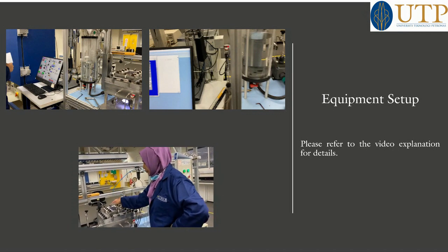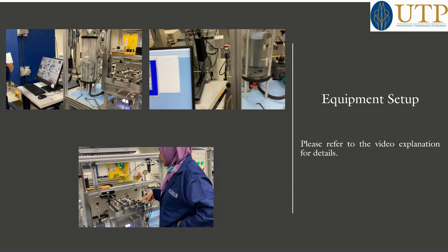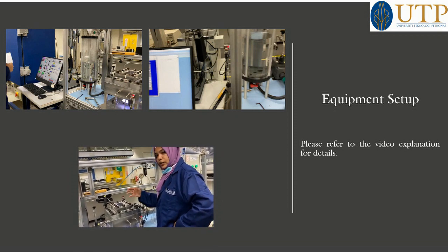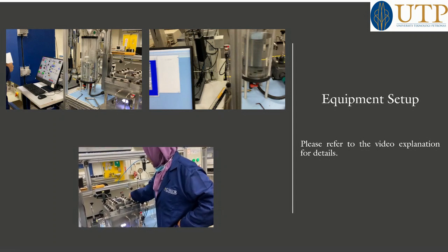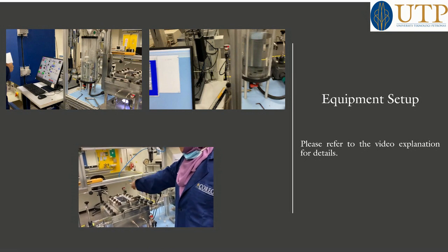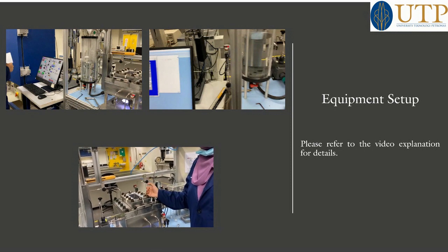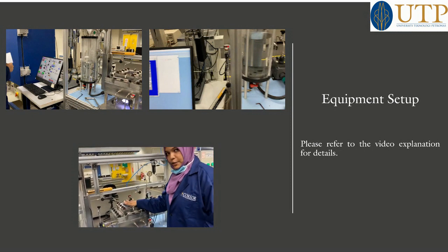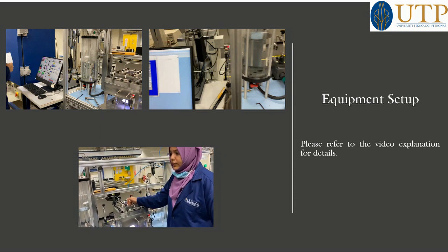That's why I have to increase the system pressure to 100 to 150, so that when the pressure comes from this carbon dioxide gas cylinder, it can't hit with 150 pressure. Maybe it will hit with only 10 psi or 20 psi, so it's okay for my glass micromodel. Let's see when the pressure increases to 100, and then we will start again.